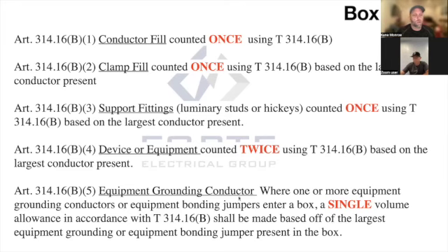So go in there and highlight your book here and put a 1 by it. 314.16(B)(5). I'm just telling you this now, assuming you're going to go back and rewatch this video, then you can go back in there and highlight it up. So you've got your wire. You've got a clamp fill if present. You've got support fittings if present. Your devices, and then your ground.